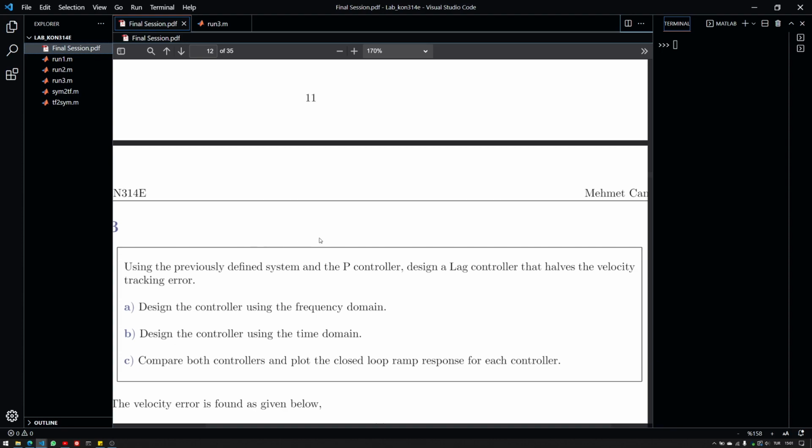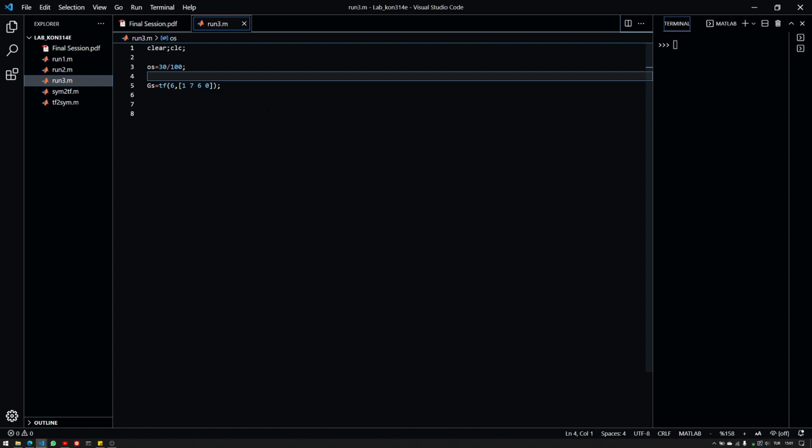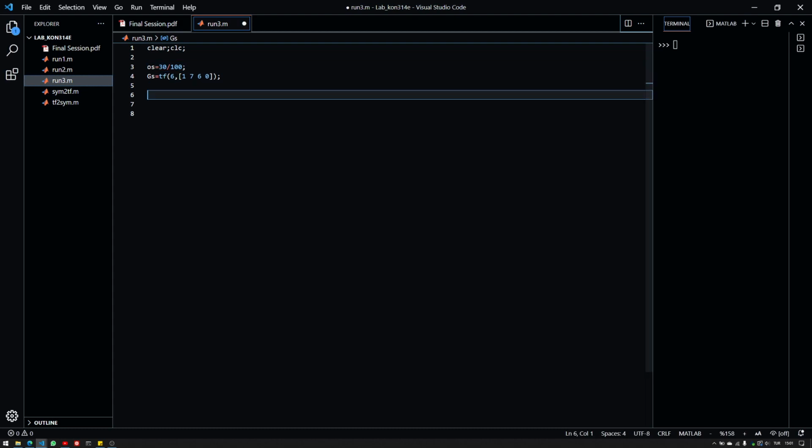By the way, the velocity constant, the position constant, and the acceleration constant are just defined to calculate the steady state errors. So they are basically helping definitions. And so how can we compute the velocity constant and therefore the velocity error?